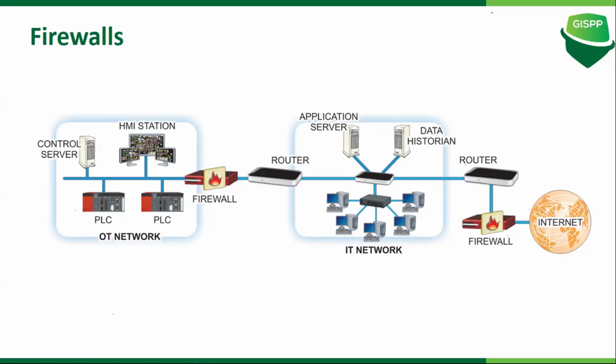And now he has got his terminal, so he will get into the router and firewall, and then he can access any supervisory control systems. So the IT security will act first, and then the OT security will come. He will land on his server or computer, whatever he has access to, and from there, we call it a jump server. From that jump server, he will route into that particular SCADA console. In that SCADA console, he can send whatever update he has to perform through that VLAN switch. So this is how he will ensure OT security and IT security simultaneously.